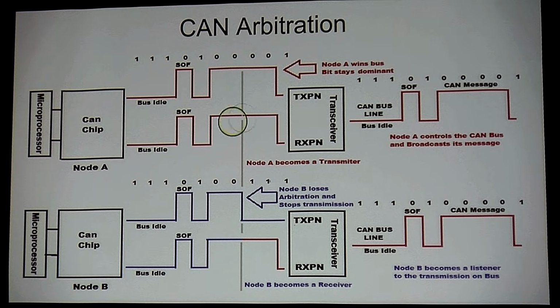So right now, in this system, this is going to be maybe a high-speed bus, right? This is a 500 kilobit, so basically this is class C. So here I've got bus idle. I've got to have 3 that are low before I can have a start of frame. So if I end the frame, I've got to wait 3 bits, and then everybody can come up. Everybody was waiting for the end of frame, and I've got 4 modules that all want to get the bus, so they all want to come up at the same time. I wait the 3 bits, and now everybody's going to go high.